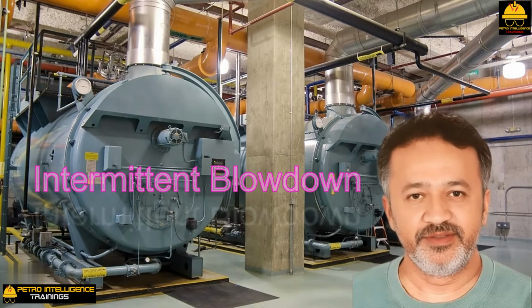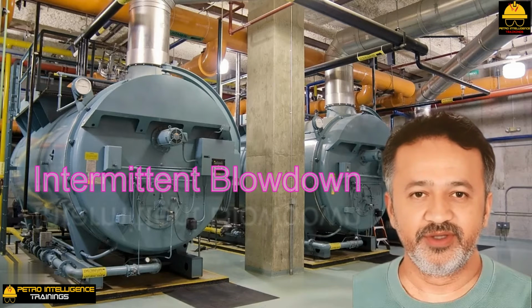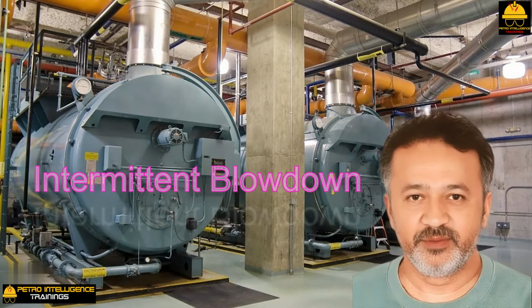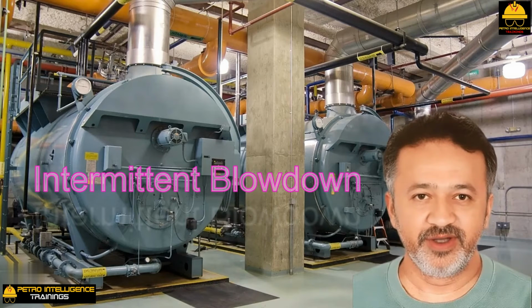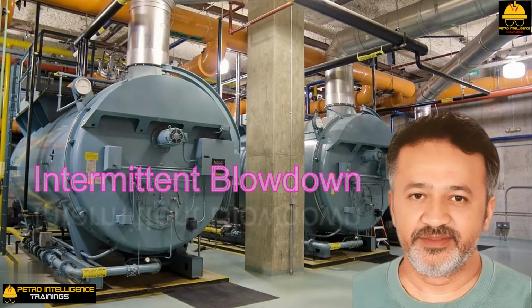Intermittent blowdown. This blowdown from the mud drum of a boiler is usually once a shift via manually operated valve. If this is automated, it is important to have the valve fully open for short periods to keep the valve clear and unblocked.